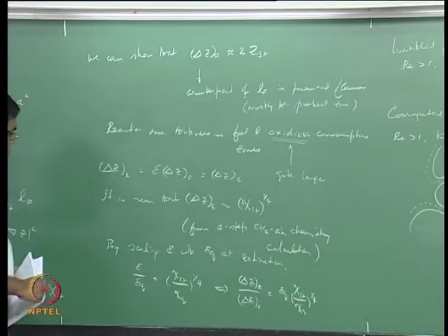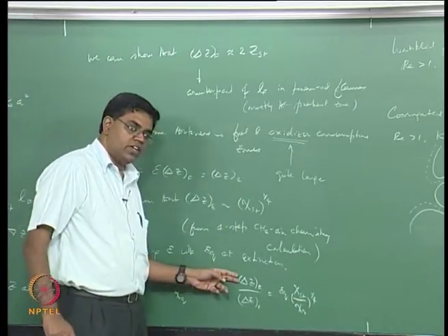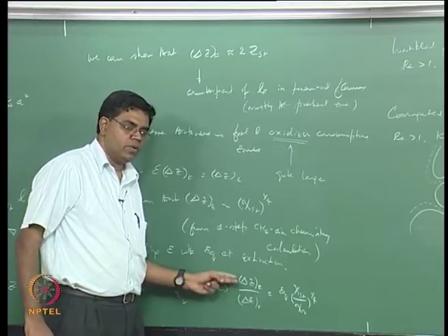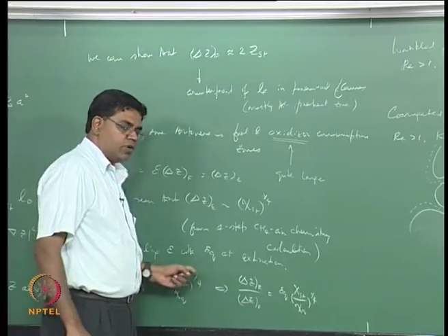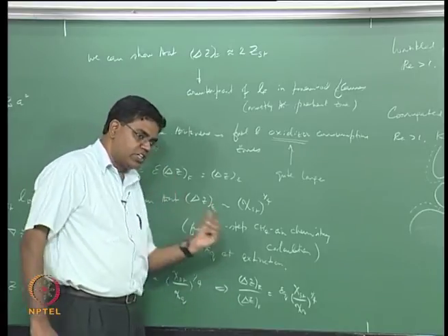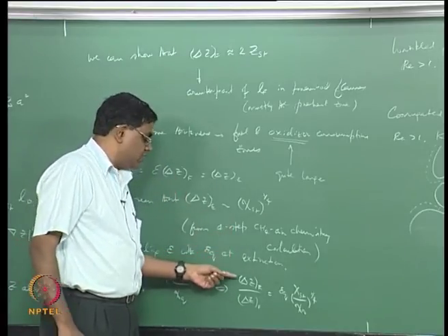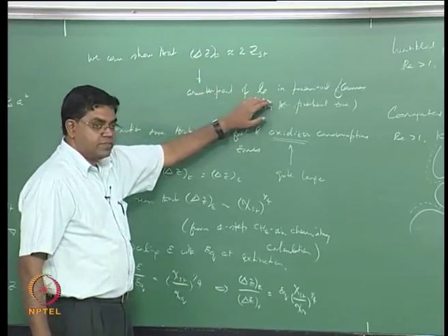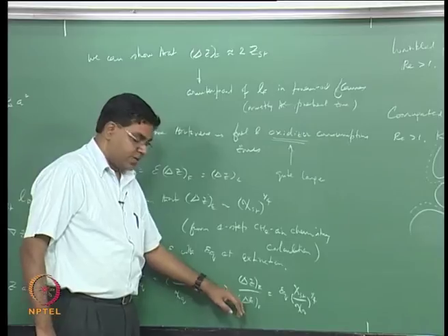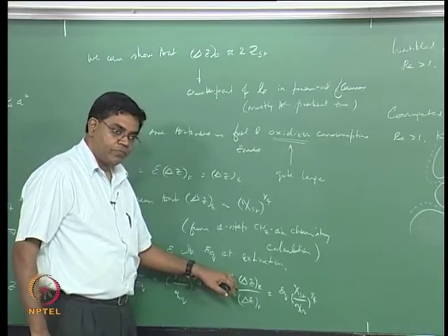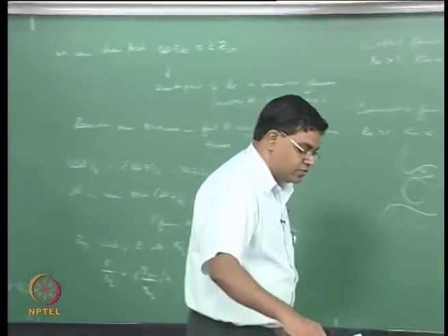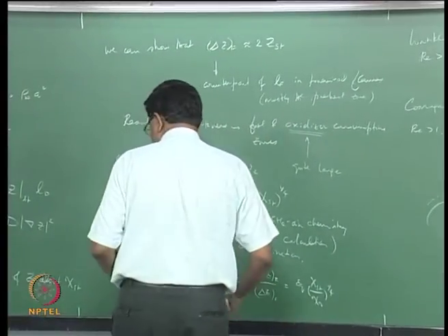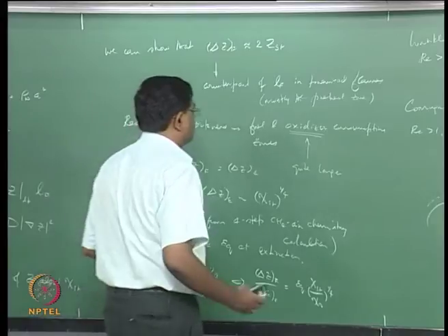Now the reason why we want to do this is that it gives you L delta divided by LF, the counterpart in the premix flames that we saw, which is the length scale corresponding to only the reaction zone thickness. As I said, this is the counterpart of LF, and this is the counterpart of L delta from preheat zones. So we're doing something very similar here as what we did for the preheat zone, premix flames.